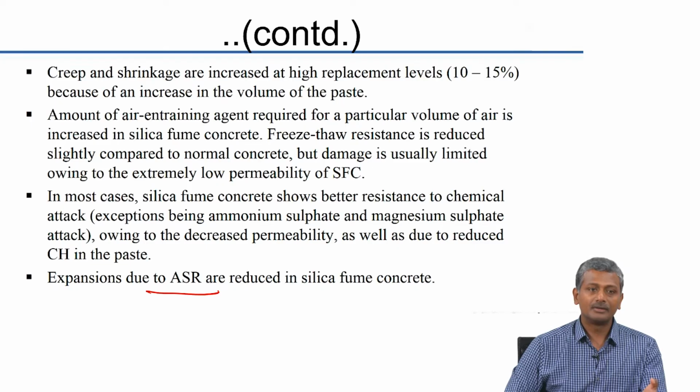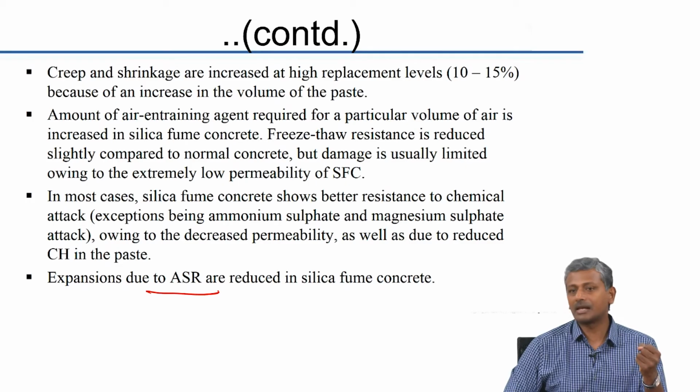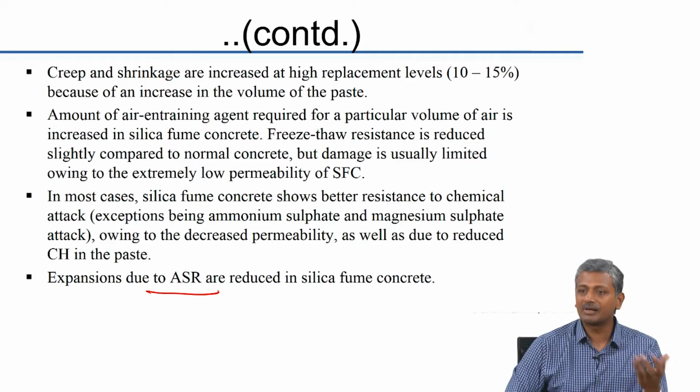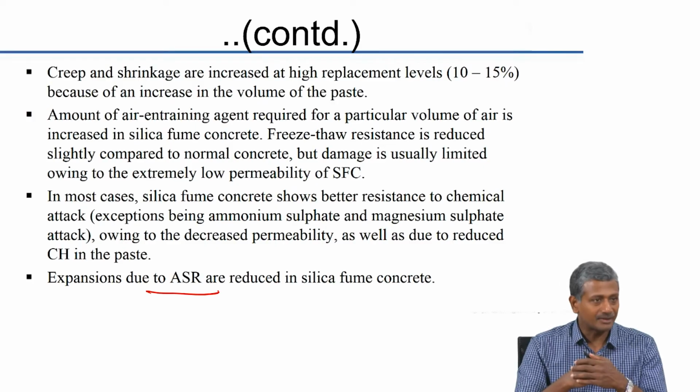Because I just told you, because of which the RCPT performance is good. What happens there? Alkalis are getting trapped in the glass. Alkalis are simply getting trapped in the pozzolanic glass or silica glass that is present in these materials. So if you do not have alkali, of course the alkali cannot react with the reactive silica of the aggregate.